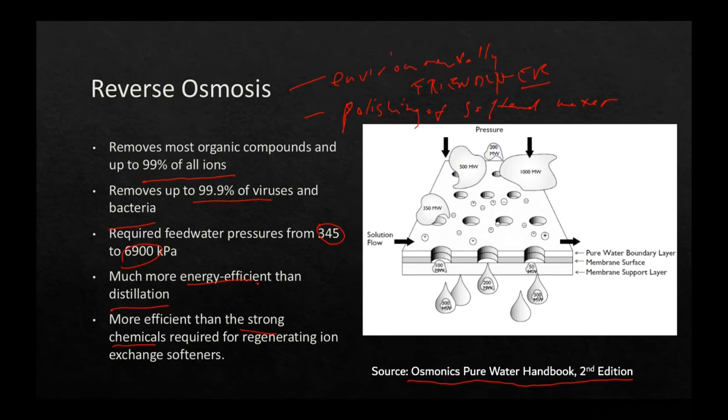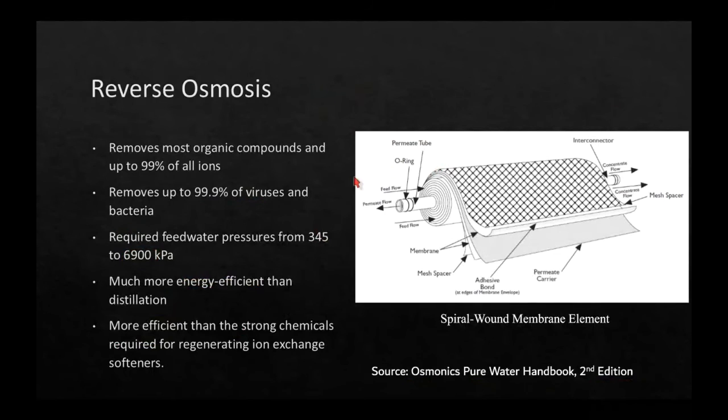What we want to do is use a demineralizer bank to take water that's already been softened, had the bulk of the hardness removed, and then the demineralizer and the mixed bed are going to do that final polish. They're going to remove all of the ions and give us ultra pure water. It's a similar situation with reverse osmosis. We're going to remove the bulk of the hardness and impurities first, because otherwise this stuff would foul the membrane prematurely. So really, we use this for polishing.